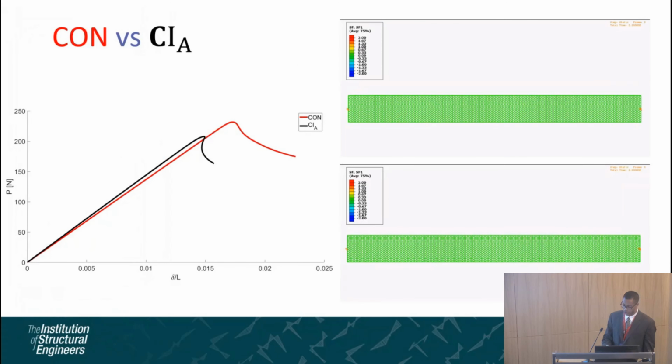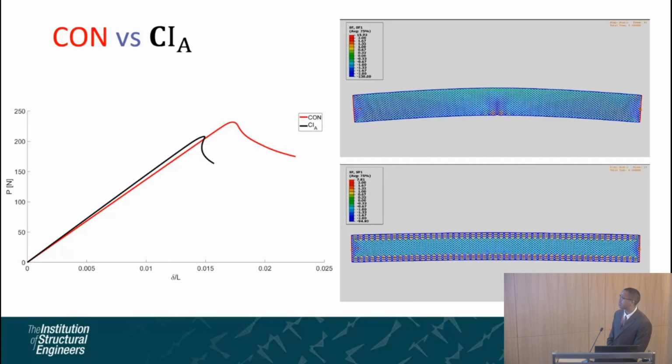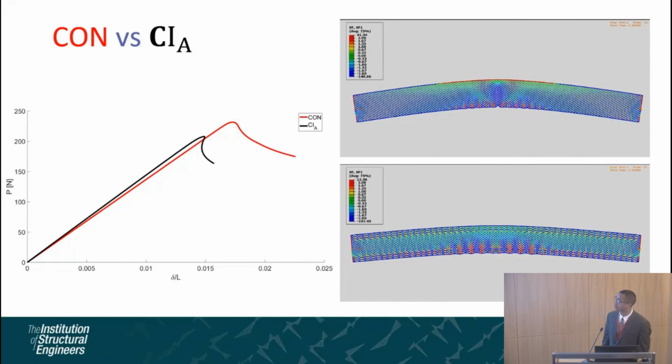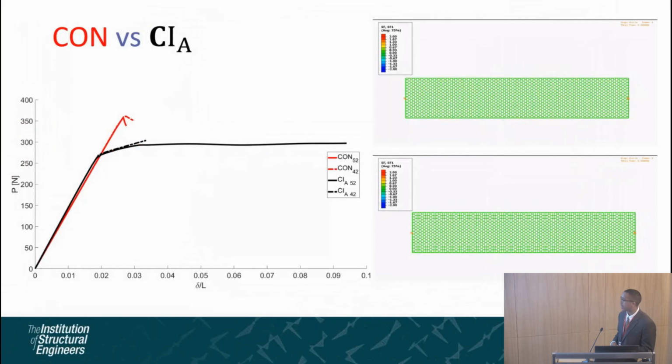Next, we have the conventional, as you've seen already, and one with the intermittent inclusions. What's interesting here is the potential for reducing the dropping capacity that we saw earlier just by having the inclusions in this manner. But we do see some snapback instability, which we need to investigate further. But what we thought was quite interesting is when reducing the panel length.